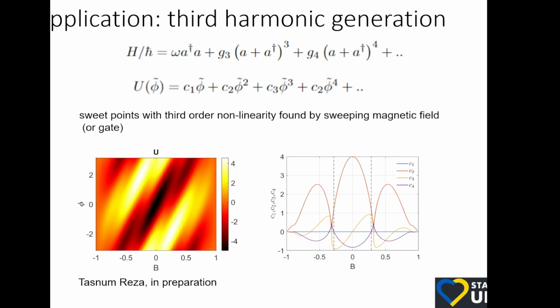There's a big junction in one arm and small junctions in the other arm. And if you put a signal through it, it also gives you the same effective current phase relationship as a single phi junction. Okay? So you can already build it out of conventional components to get these third order terms. And the third order coupling between microwave signals, or the amplification if you pump it with another tone, is more efficient than the traditional scheme which relies on fourth order, right? Just from the fact that it's one order less, it's more efficient.